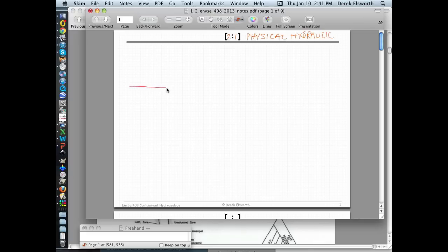So here's the idea. You have ground surface. You have a water table that sits below the ground surface. Above here is partially saturated soil or rock. And below here, all the pore space is filled with water. And below this you may have a different bed, such as maybe a shale, something that has very small pore space in it. Shale is just a low permeability rock.